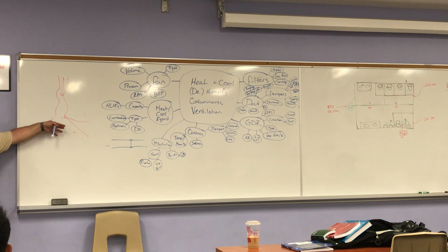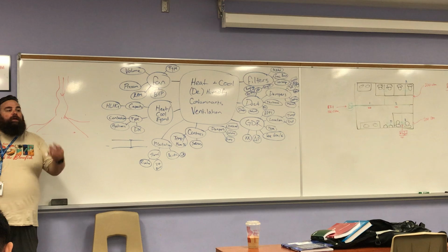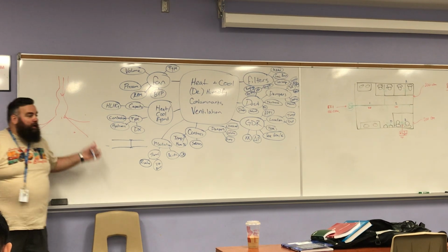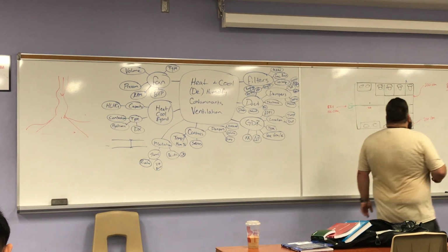So the same idea here when we're trying to keep contaminants exhausted: we want that air going fast enough that none of it comes out inside the duct. We want to carry it with us. So we're incentivized to reduce our duct size a bit.